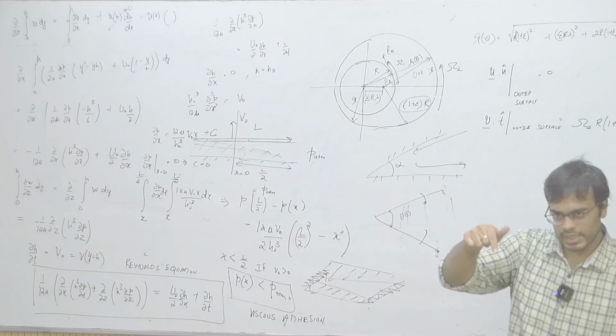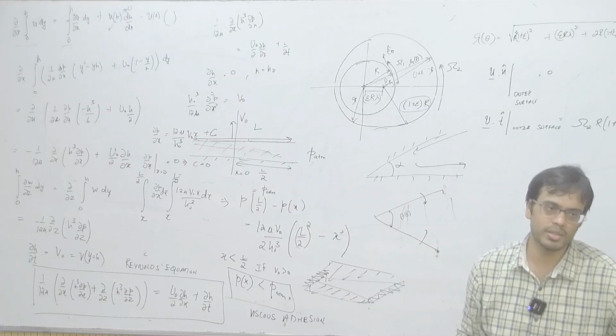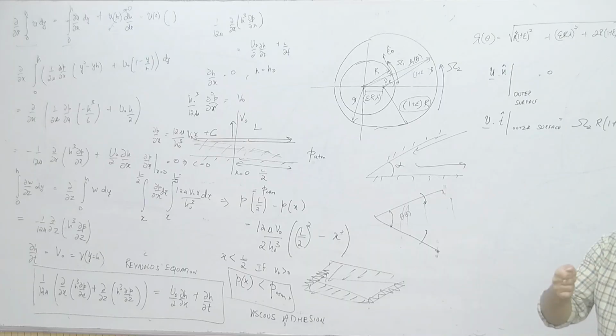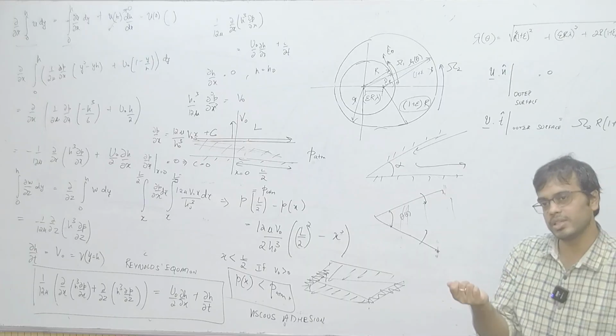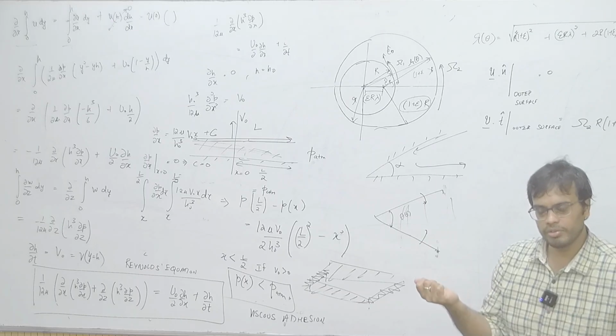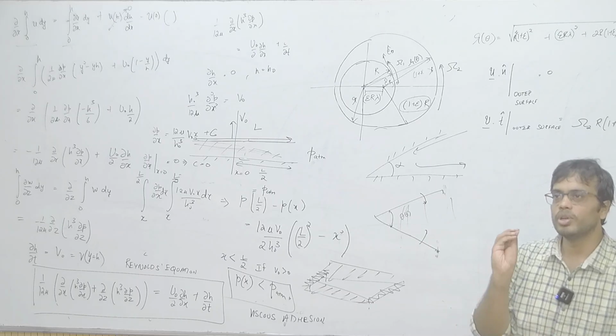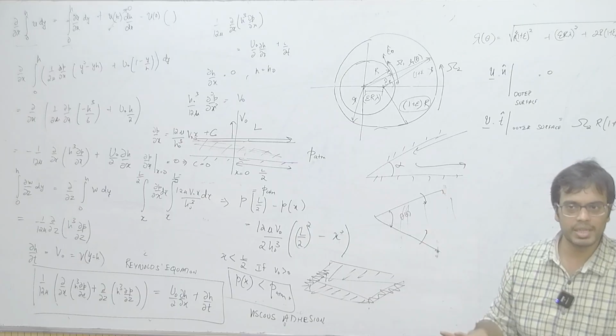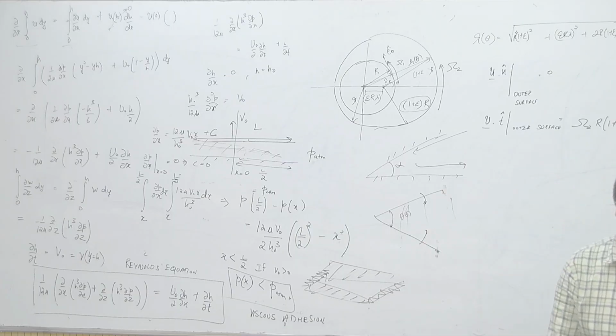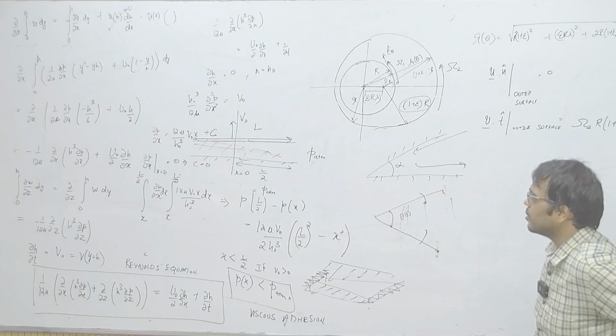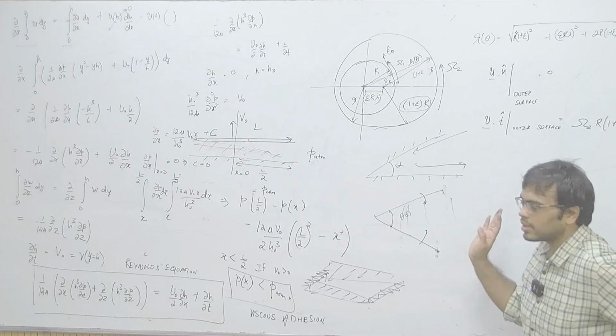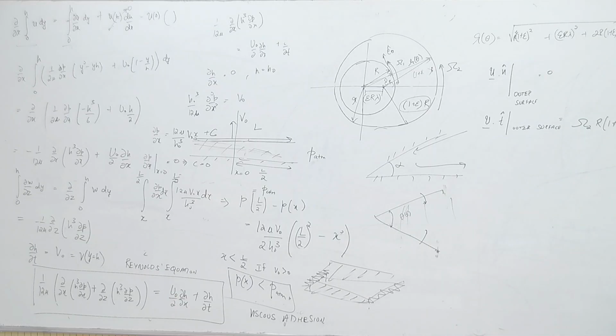He used that extensional flow, derived the extensional flow solution, and derived the effective viscosity of a suspension. If a normal fluid has viscosity mu, and you disperse some very small spherical particles in that fluid, then what is the effective viscosity? So, these things find applications almost everywhere.